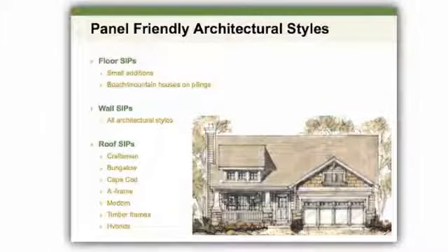But we also have what we like to refer to as panel-friendly architectural styles, which very conveniently incorporate SIPs into their design. And you see this list that we've listed. It includes things like bungalows, the craftsman-style houses. We move to Cape Cods and A-frames. You get into these designs where insulation moved up into the roof as opposed to a flat ceiling works very, very well. And of course, that's what SIPs do incredibly well in a roof application. They take the insulation, they move it to the roof line, and they give us additional living space.